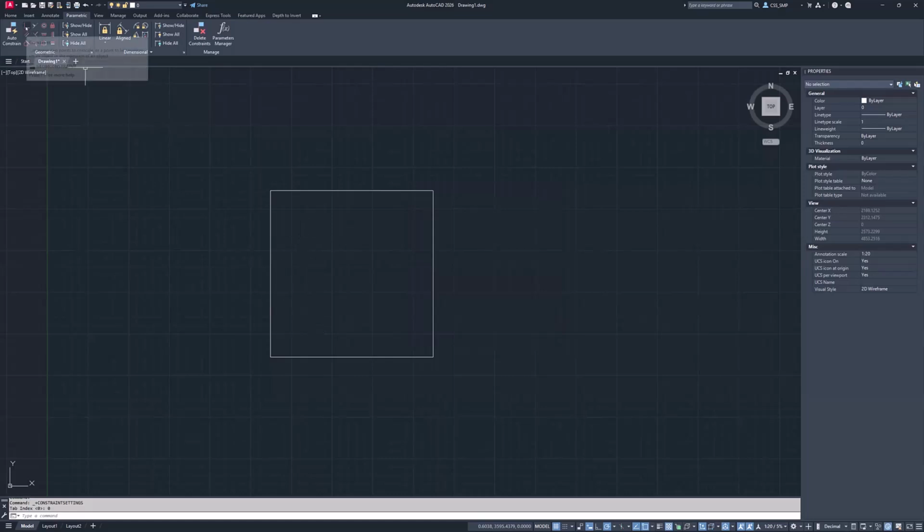I'm going to come up here to coincident, and on each corner, you'll see when I'm near a corner, it's got a little glyph that shows on screen, which is red. If I go along the line, it will snap to the midpoint. You'll notice that when we are adding constraints in AutoCAD, let's do an arc, just for an example. Actually, I should be able to pick that. So you'll see that we can snap to the endpoint, we can snap to the midpoint and the endpoint. So there are certain snaps that are available in our constraints.